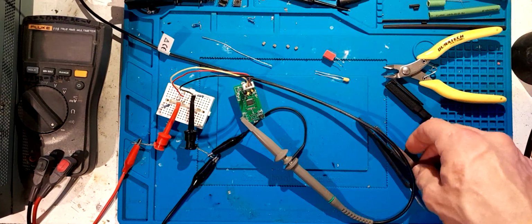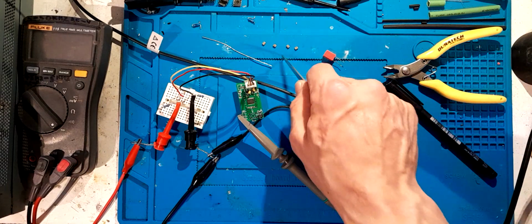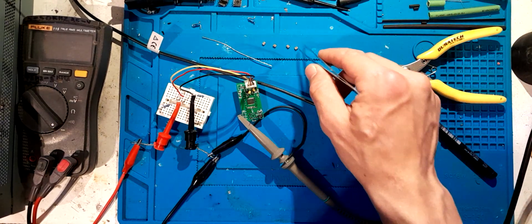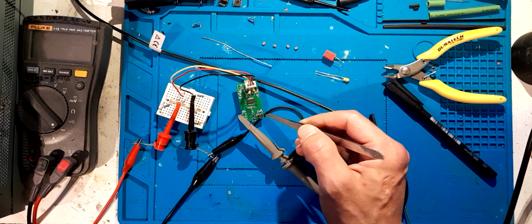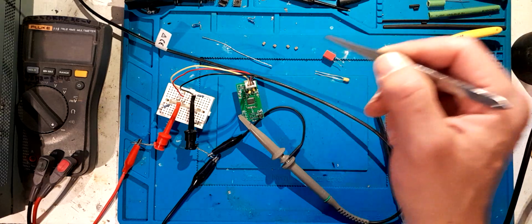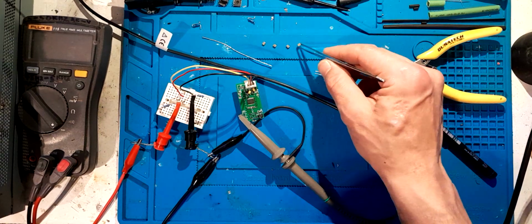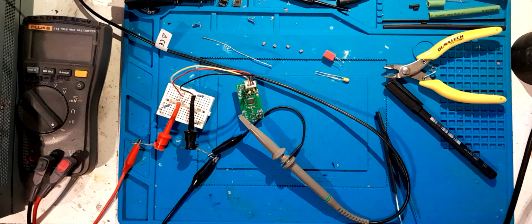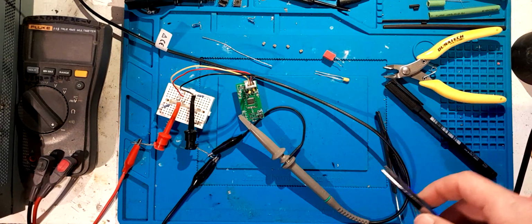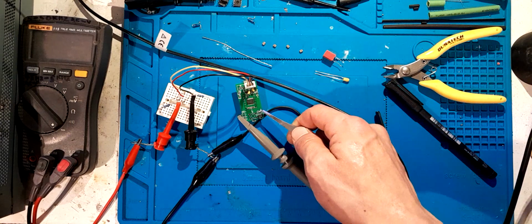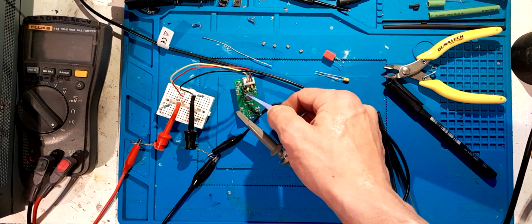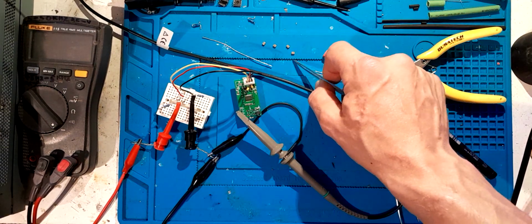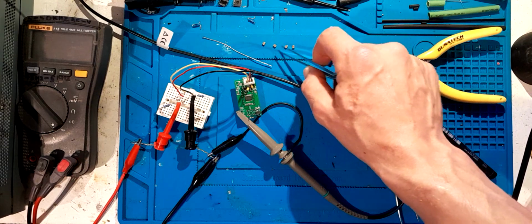Okay guys, so I've grabbed these 4 10 microfarad SMD caps. These have got the same properties as this capacitor in terms of frequency response and ESR, except for better ESR because these are a higher voltage rating. So these are the capacitors that like to go up above 100 kilohertz, up into the megahertz range. Not that that's really critical there like it is for the VCAP, for the internal voltage regulator, but it's still fairly important, so I chose the better quality ones. And there's 4 of them there.